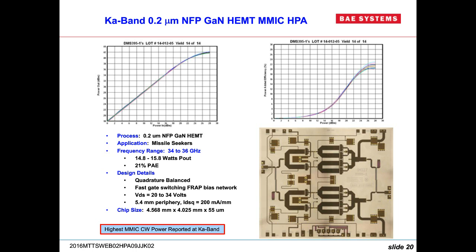If you could somehow shift the doping profile so that you're at the center of that bell-shaped curve, the even order harmonics would tend to self-compensate, and you'd only have the odd order to deal with, and the intermods associated with that. So there's room at the transistor level to deal with it.